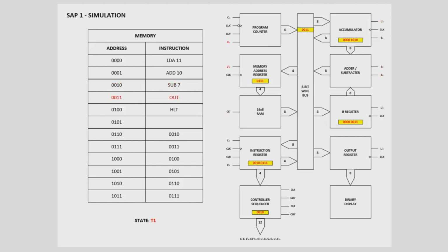The conditional jump is a jump based on certain conditions such as zero or carry flags. As for the increment and decrement operations, the increment increases the content of a register by 1, while the decrement decreases the content of a register by 1. The halt operation stops the processor, bringing it to a halt. The control unit generates control signals based on the opcode, directing the flow of data and operations.